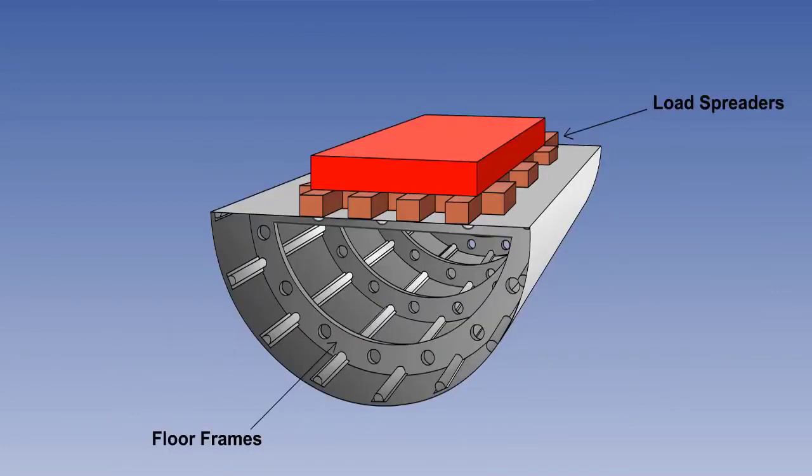To overcome a problem of concentrated loads or items with sharp areas being placed in the hold, 2-inch thick timbers are placed between the load and the floor. This method assists in spreading the load over a large area and protects the floor from damage due to sharp items.